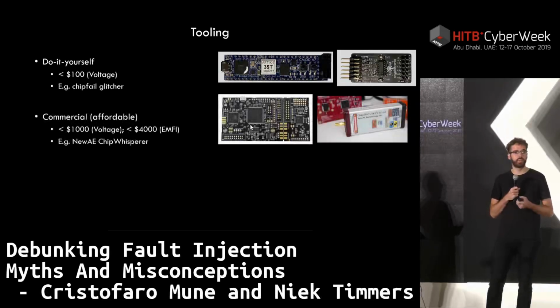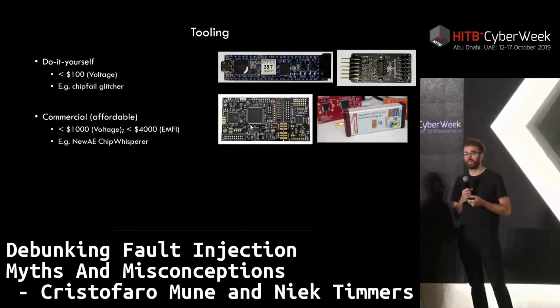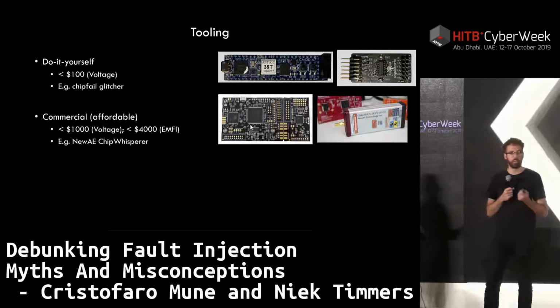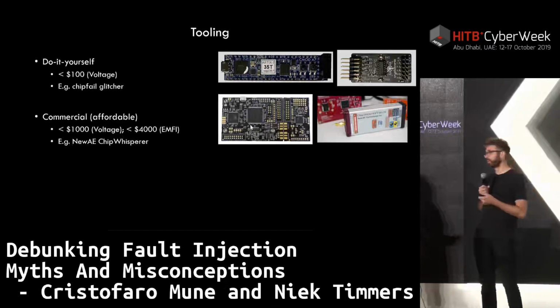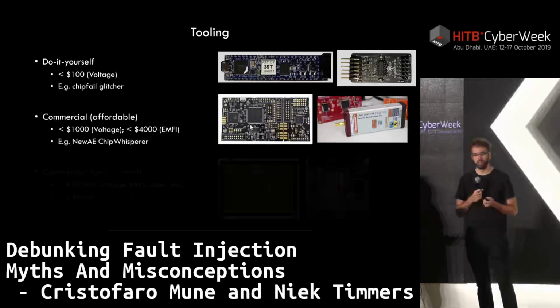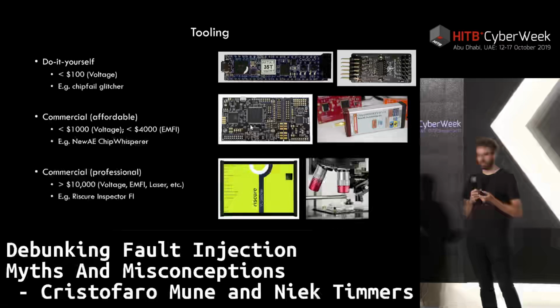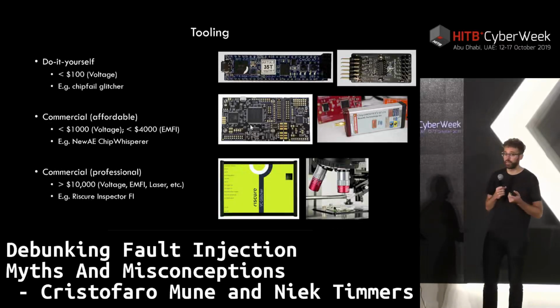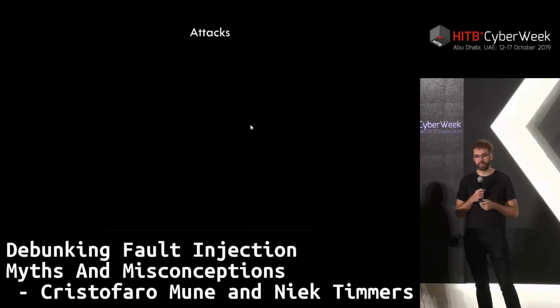Also, there's nowadays affordable commercial tooling available. For example, the products that are created by NewAE, the ChipWhisperer, can be simply bought for less than $1,000 with some extras that you need in order to perform these attacks. And they allow you to perform these fault injection attacks with off-the-shelf hardware, which is something you could not do 10 years ago, because then only professional tooling was available, which is quite expensive. The advantage of this professional tooling is that it supports a wide variety of injection techniques. But we'll talk a little bit about that later.